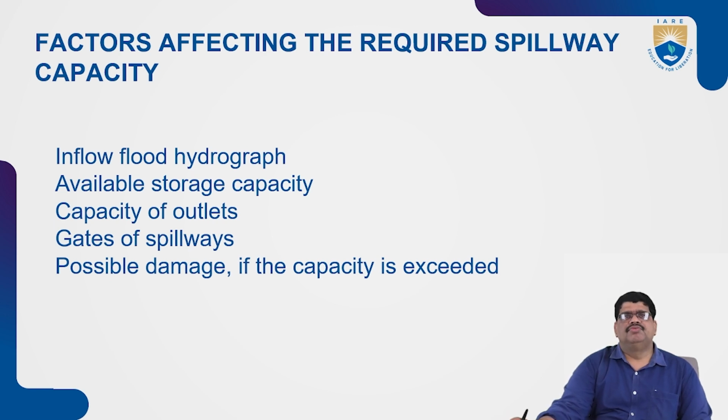The first one is inflow flood hydrograph. We have to know how much inflow of floods can come during the heavy flood rainy season. That's why we have to calculate the hydrograph, which affects the required spillway capacity. Next, available storage capacity.